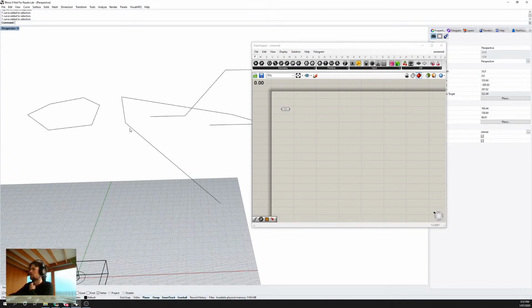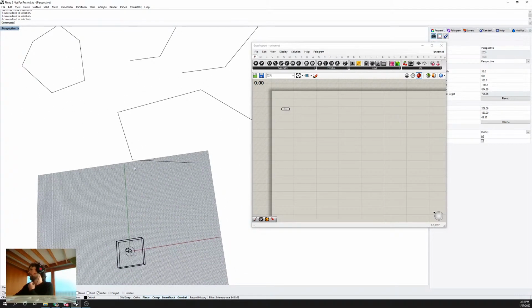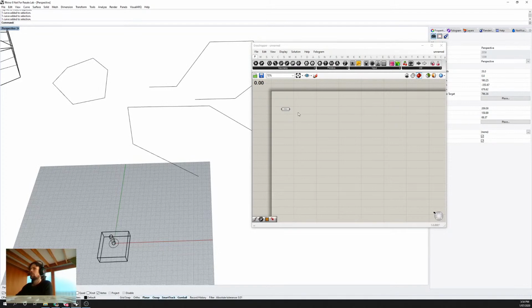and also we want to orient it in the bend plane. There's tons of ways we could do that in Grasshopper. You could go through and break the curve up into its different points and then build planes from those points. You could go through and find perpendicular frames of discontinuity, work it out from there. The easiest way that we came up with doing this is to fillet the curve.